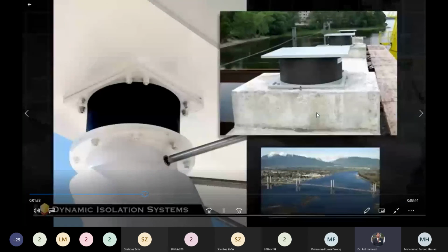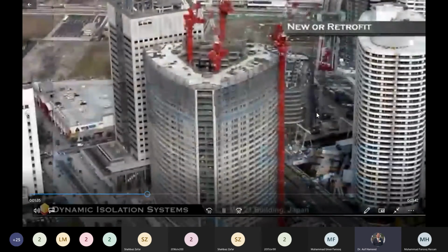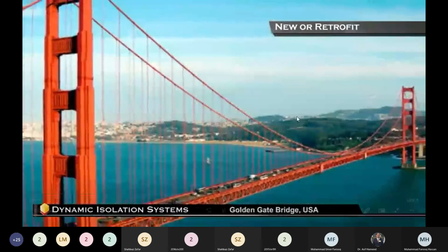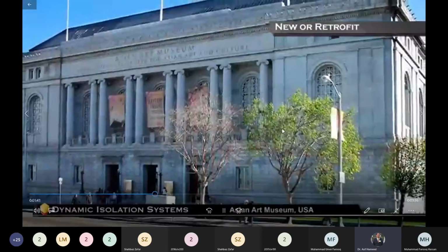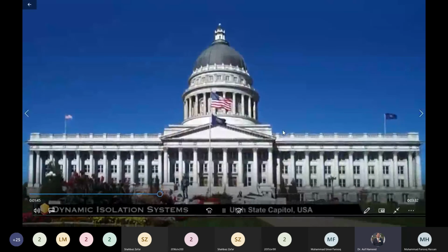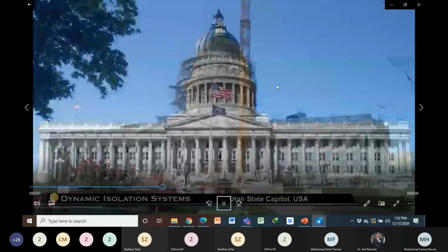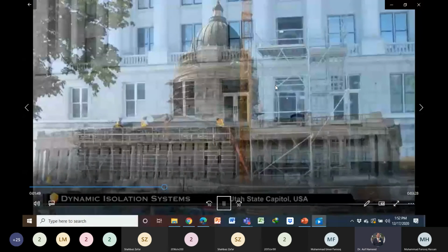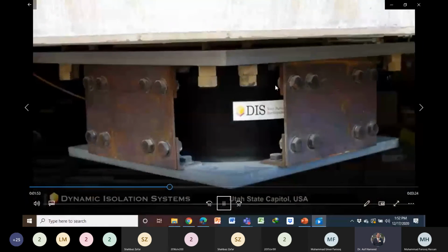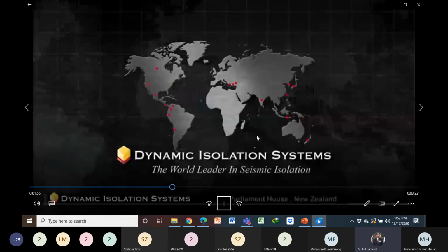And these dampers we can use under the foundation. Maybe you have seen these kinds of dampers; in bridges, they're commonly used. We have lead rubber bearing, elastomeric bearing, simple pendulum bearing, friction pendulum bearing, sorry.